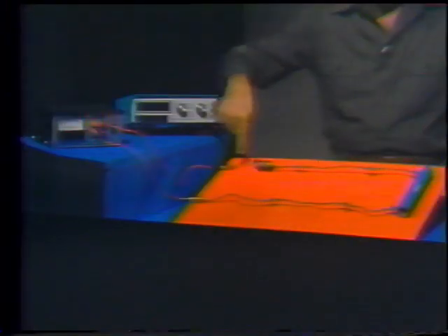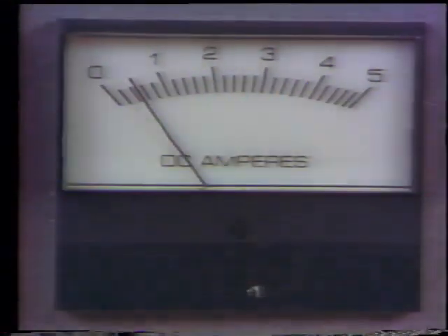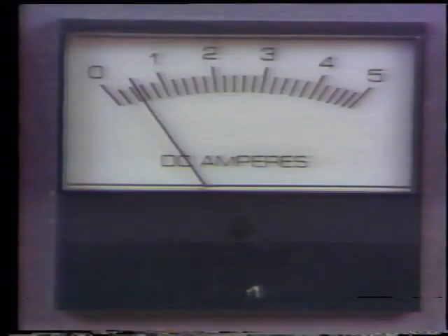First, let's look at how voltage is distributed in a series circuit. This is a series circuit. It only has one current path, and when the switch is closed, current can flow through the circuit. There's about ½ amp flowing through here. This black box is what we call a regulated power supply. It provides a more accurate voltage than a battery. The switch on the black box turns the power off and on.